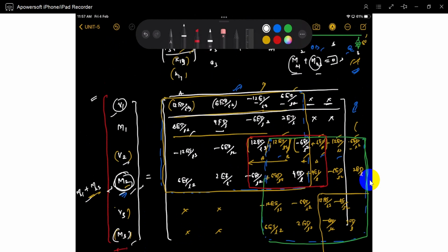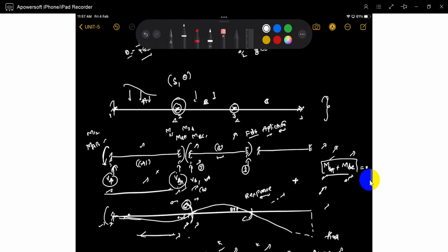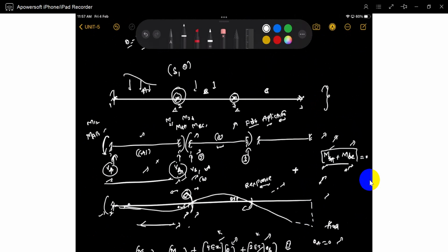The same will go for the flexibility matrix also. Force, response, same thing. Here we apply a load. We restrict every degree of freedom. We find out the forces developed, which come outside. Later we release the degrees of freedom, and the forces developed are the resultant. In the flexibility matrix, if you apply a load and we release the degrees of freedom, we want to find out the deflections and rotations. Keep them aside.